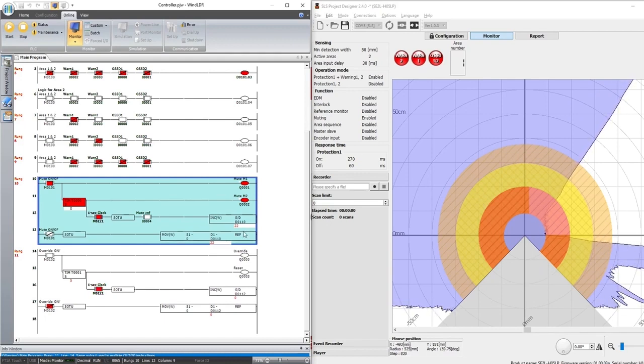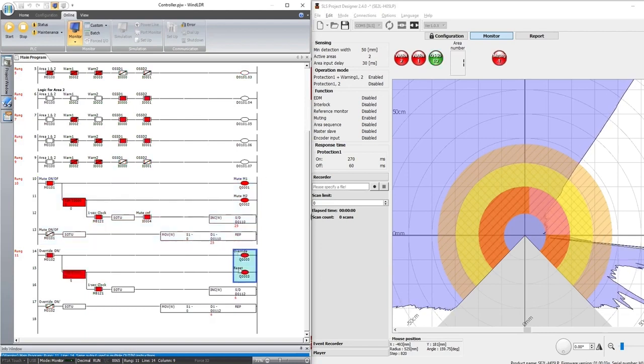For that, I'll switch on the override signal. So the override signal is in function state now. Its functionality is switched on. So again, the muting function has come back and the OSSD signal is in off state. Sorry, it's in on state. To make it off, either the timer has to reach 60 seconds, or I need to switch off the override function.